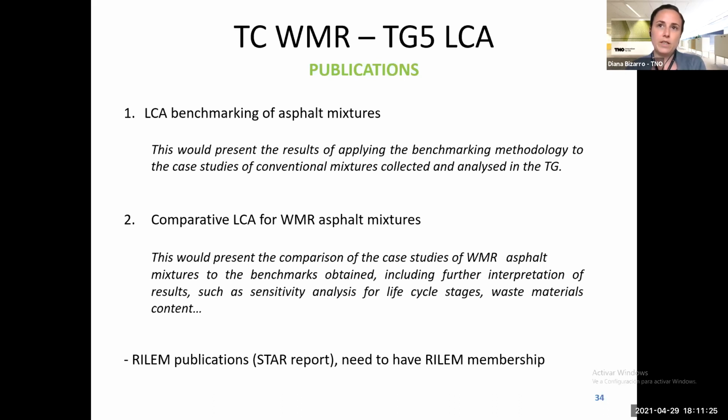But then another idea, well, there is a problem with using data from lab scale, which is usually different from the industry level, where it happens differently, or it is more efficient, or they use different equipment to filter. Sometimes you can just use the limits provided in the legislation to model those emissions, and then take the maximum values for the modeling, and then you have a conservative approach.